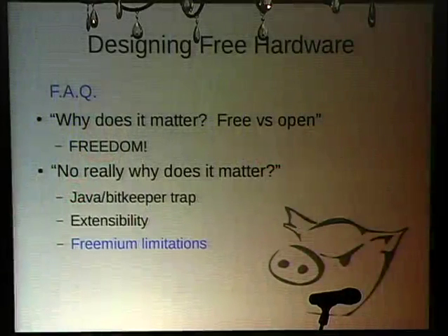And we'll get more into that in a little bit here. And then finally, there are limitations. Even though it's free as in beer, like I said before, there's the 4x3 4 inches squared you're allowed to make your boards. You're only allowed 2 layers. You're only allowed so many traces. The vias are actually octagons. There's lots of weird issues with their software, and it's all on their terms. It's just whenever they want to give you a new limitation or change.